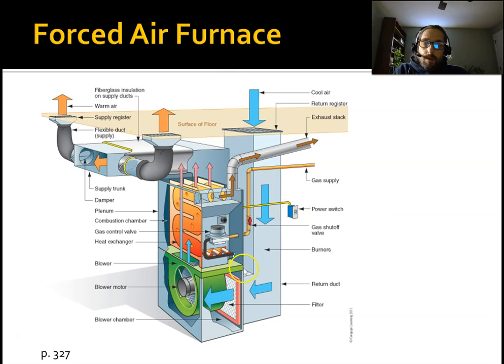And then your other system is the whole combustion process. We start with our gas supply. This is a natural gas furnace, but this could be propane or oil, although oil is slightly different. You bring your fuel source in, and it burns here in your burners. You need oxygen to facilitate that reaction, as we went over in the last lecture. It's going to get oxygen either directly from the outside, which isn't pictured here, or it's just going to pull oxygen in from around the furnace.